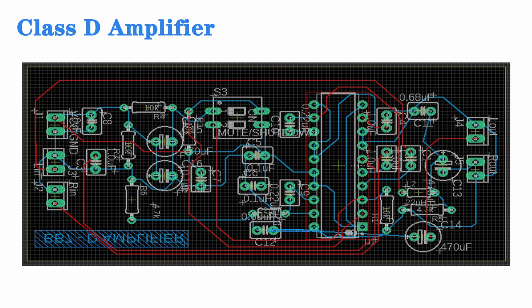The output stage has 2 woofer channels that are first led through a low-pass filter stage. Also, there is a gain control which is not used, so it is 0, 0. This will give a typical 20 dB gain.